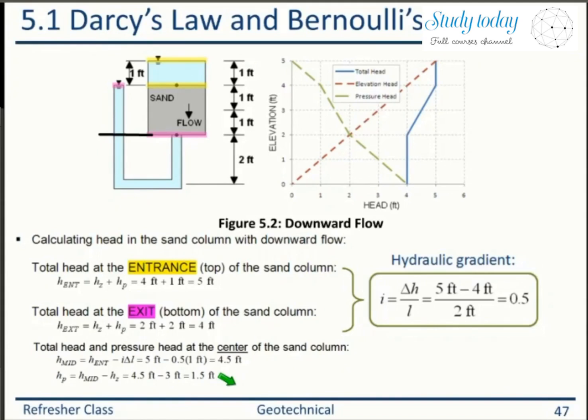How is H equal to for the bottom? You insert the piezometer here and you know that the piezometer will show the pressure head at that point. So in this case it's given, right? From here to here, what is the height? Can you tell me the height, James? It is 2 feet. Therefore your pressure head is 2 feet. It is from the pink line, correct?